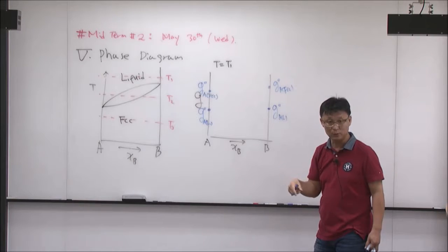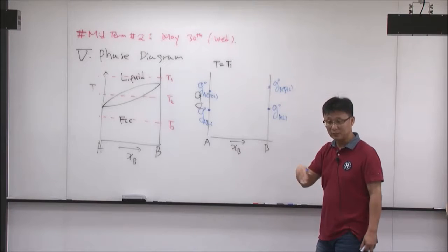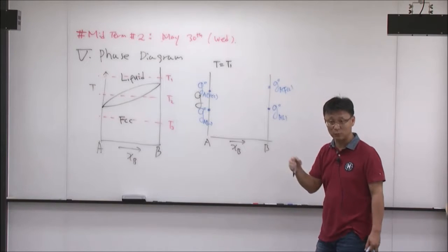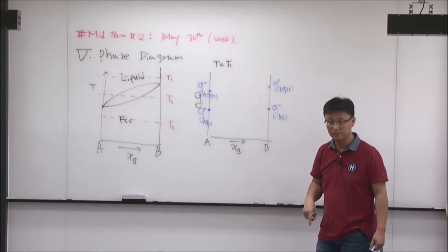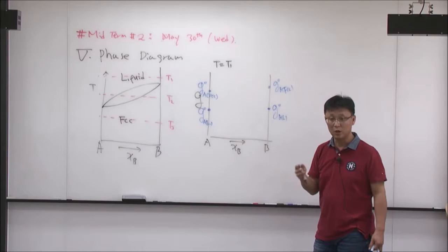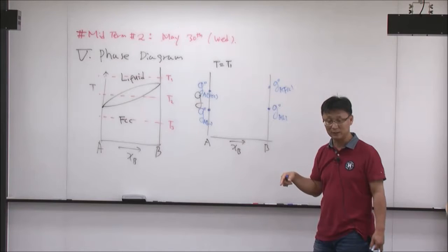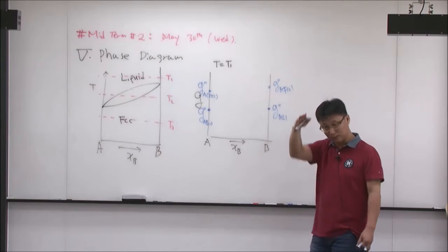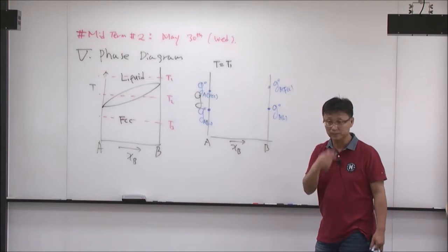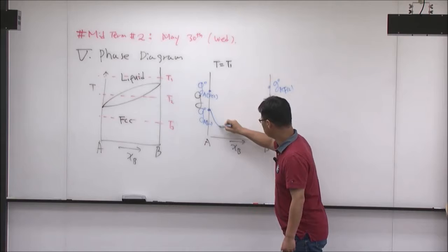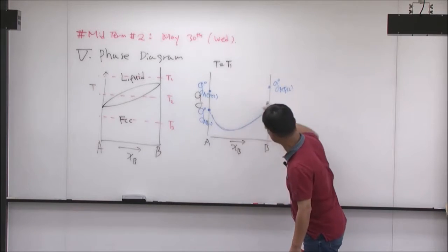and that's when the activity coefficient equals 1 for pure A, pure B, or A and B. And when your actual Gibbs energy is more negative than the ideal case, your activity coefficient is less than 1, and in that case, the curve should be more negative than the ideal case. Yeah? Is it okay? Or, if this is a regular solution, so omega AB is a negative parameter, it means you should have lower Gibbs energy than the ideal Gibbs energy. Okay? So, whatever it is, we don't know, but at least it should connect from the pure A to the pure B.